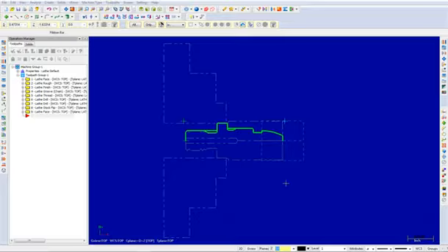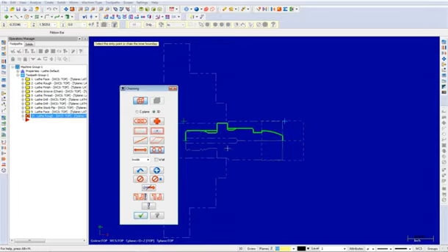Now we will rough the part. Select the rough icon and pick the entities as shown. A branch point will be encountered. This is because the geometry is broken and Mastercam has reached an intersection. A path needs to be specified to complete the chain. Select the entities as shown to complete the chain. Once selected, choose the OK button to exit the chaining dialog box.